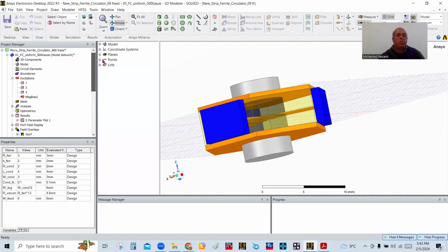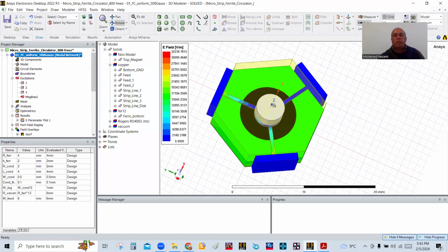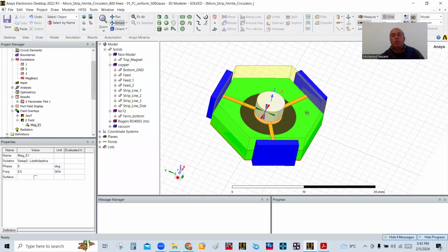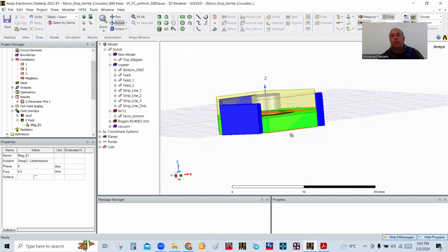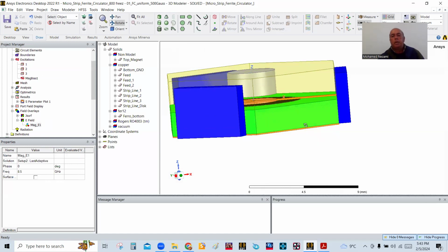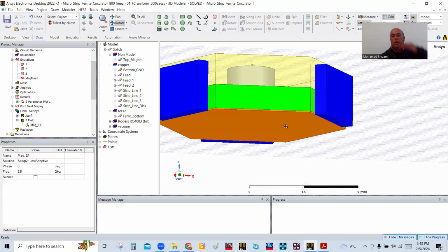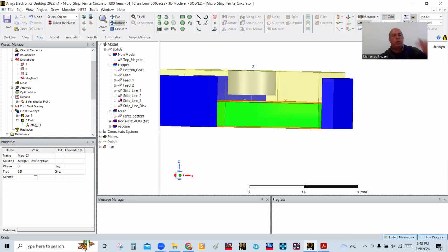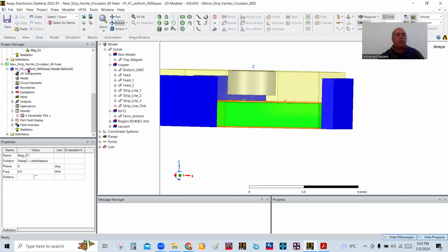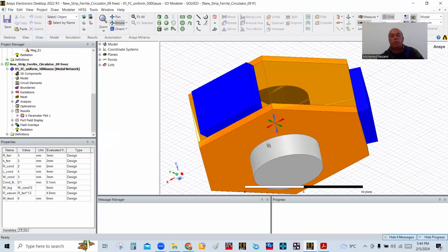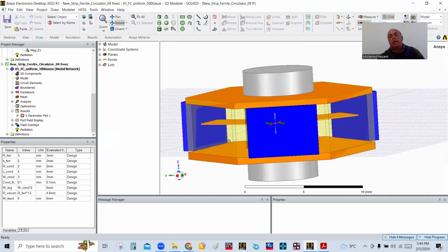In the first one in here, let me get rid of the electromagnetic field picture so you can look at the copper clearly. So you have a substrate, okay? You have a ground in here. That's the ground here, and you have a substrate, and on top of the substrate is this printed line. So this is a microstrip because it doesn't have an upper ground plane as well. I'm hoping that you're familiar with strip line and microstrip line because I'm not going to cover that. The strip line is the other way around.